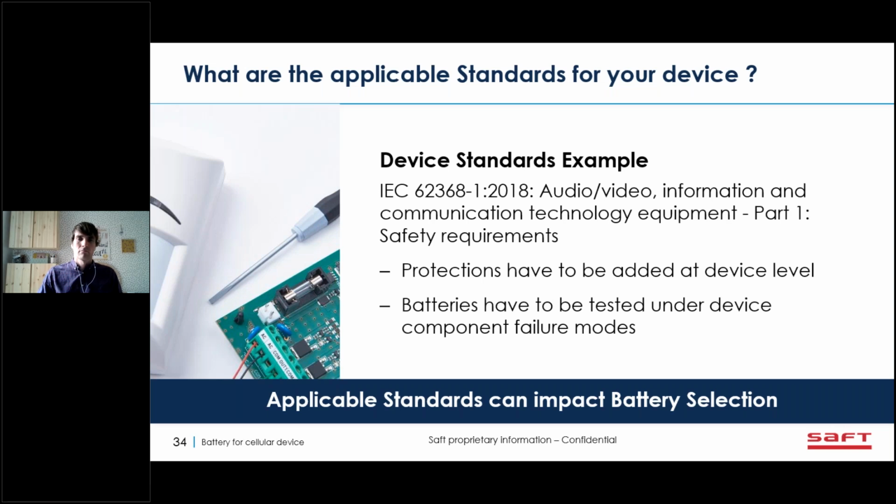For example, if you add protections at device level, fuse, resistance, whatever it is, it can generate additional voltage drop. It will consume more, so it can have an impact on the selection of the battery. So you need to really, during the development phase, have in mind what could be the applicable standard of my device, and does this standard impact my electronic device?